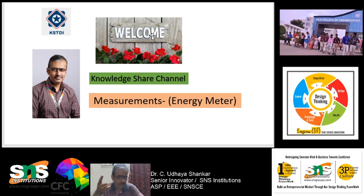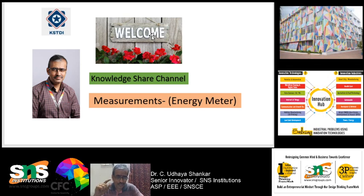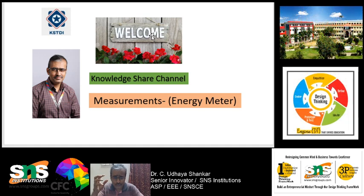You may ask me one question. What happens if I connect 2 kilowatt for half an hour? That also will be 1 unit, that is 2 into 0.5. Or 4 kilowatt if I connect it for 15 minutes, that also will be considered as 1 unit. So it's nothing but how many kilowatts are connected for how much duration. It's just a multiplication of both.